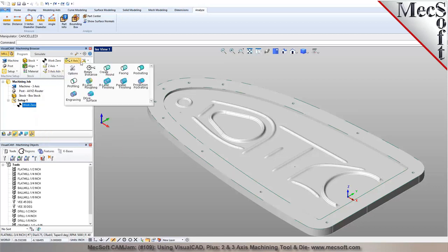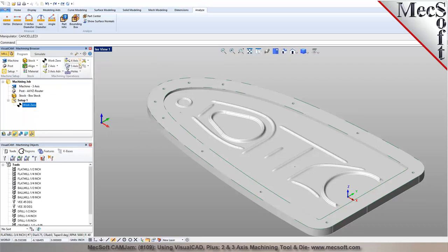The 4-axis methods are included in the Pro. You also have access to whole machining. The simultaneous 5-axis is not in the Pro. You can still do indexed 5-axis, where you can do positional or 3+2 machining. And the Pro also includes fixture offset programming. You can do instancing, where you can basically have a pattern of these parts, like an XY instance of these parts created. So you just program toolpaths in one and then you instance the rest.